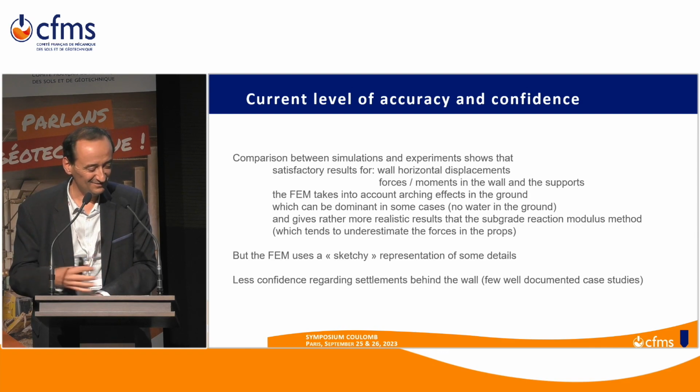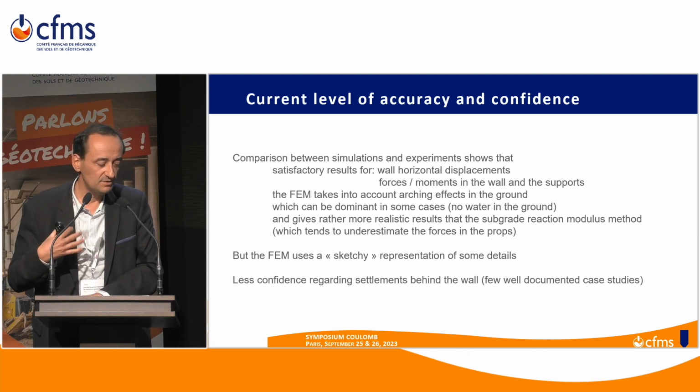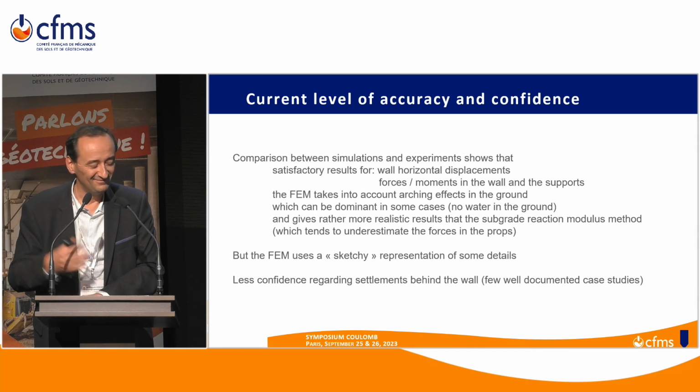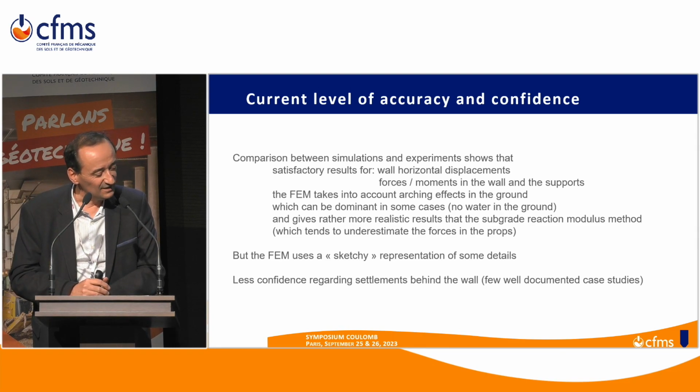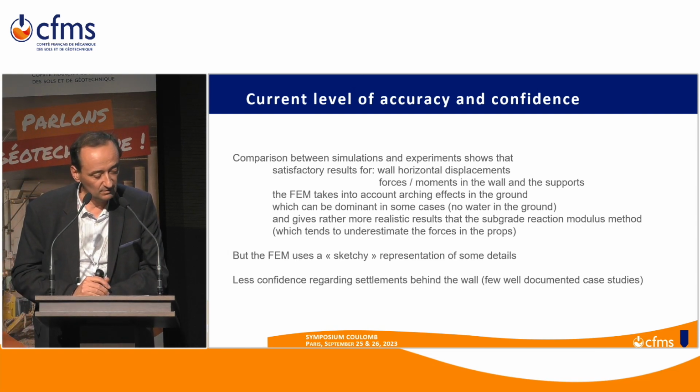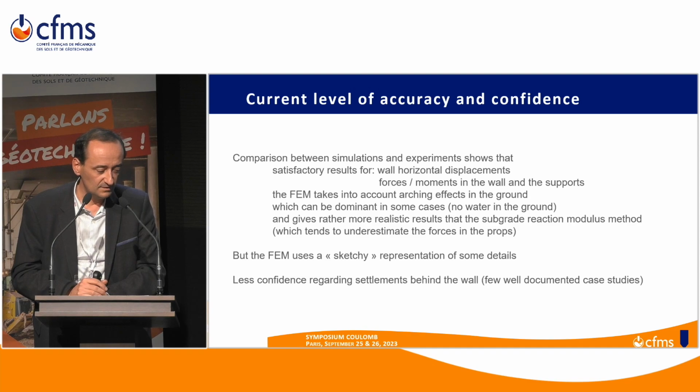So we know that the results are rather satisfactory for the horizontal displacements of the wall and for the forces and moments in the wall and in the supports. We also know that, well, at least I'm convinced, that the finite element method takes into account arching effects in the ground rather better than other methods, and especially in some cases where arching can be more spectacular, more important.